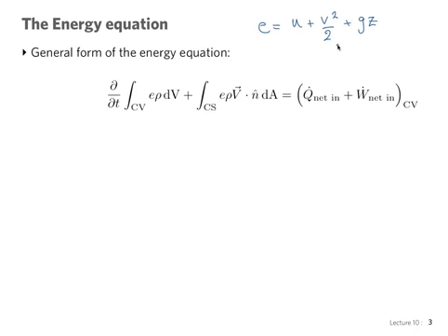There's pressure work, there is shaft work when you have the fluid interacting with rotating machinery, and viscous stresses also can do work. But we're often comfortable selecting our control surfaces so that they're perpendicular to the velocity, and if they are, there are no tangential forces that we need to account for.